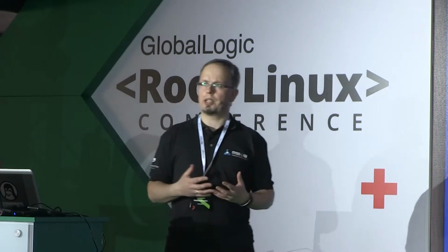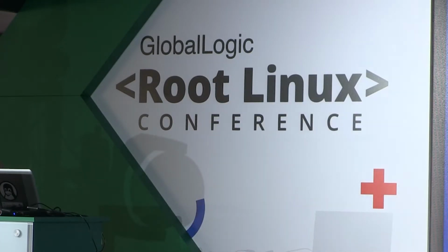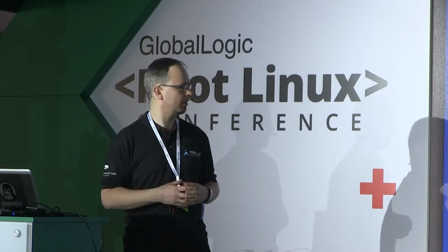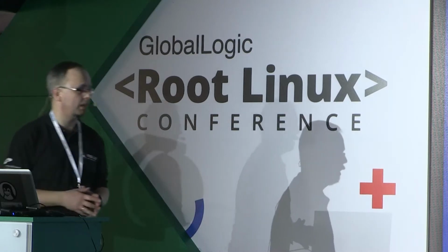We will test our gadget using the USB serial generic driver. That is, the USB serial generic driver will create the ttyUSB-something device for us, and we will expect to read back from that device whatever we write to it, except that it will be all capital letters. So now let me go through the first part of the script composing our gadget.